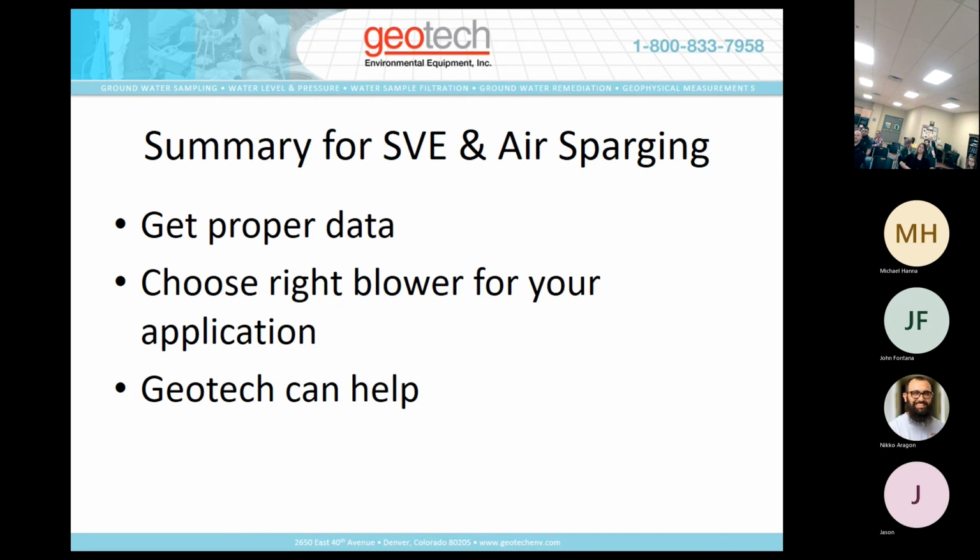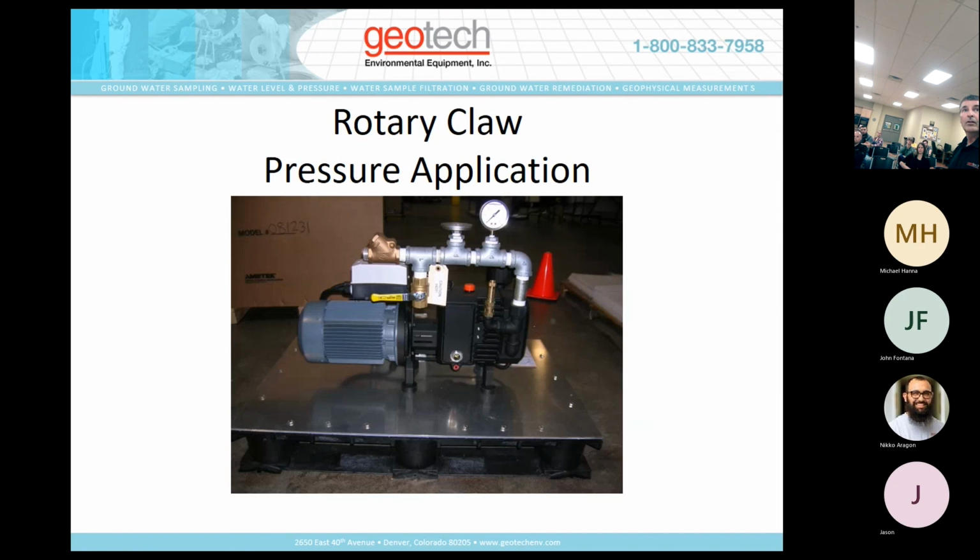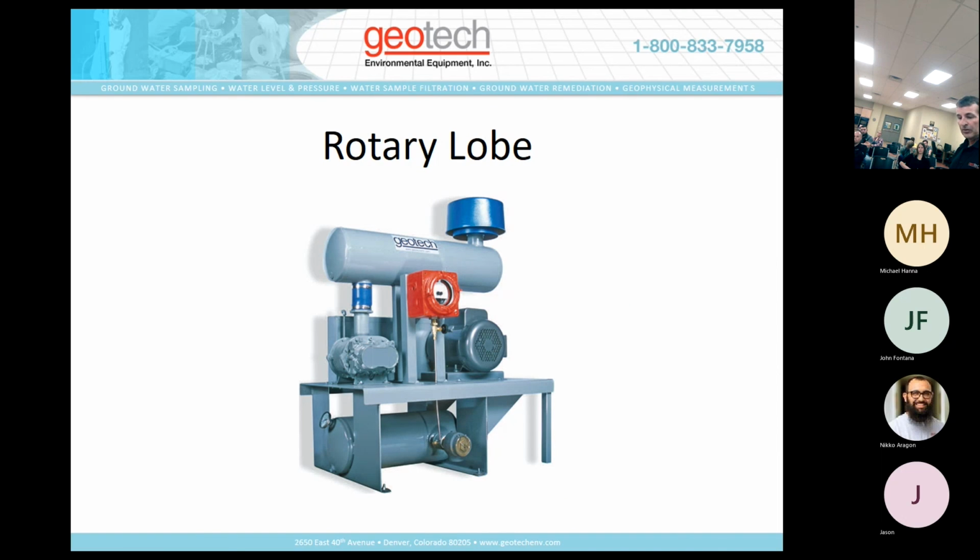On the setup where it had a filter, what is it filtering? Just the exhaust? No, it's filtering the inlet. So just cleaner, drier air? Correct, if there's silt or any kind of fines in the airstream. Especially maybe in a humid location? Right, it's more for fines and solids. I imagine those belt-driven ones are even louder. Yeah, but as you saw in the picture, it comes with a large muffler to quiet it down.